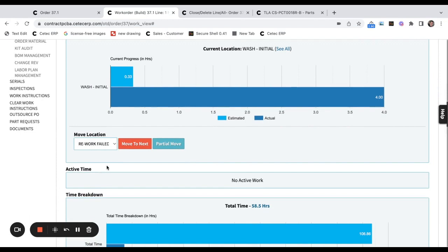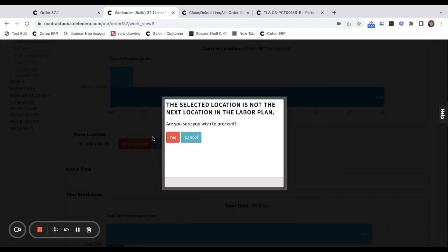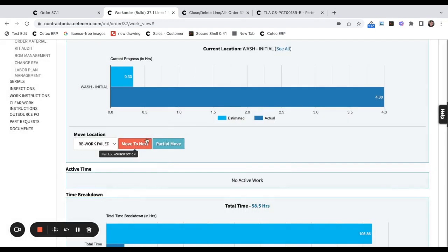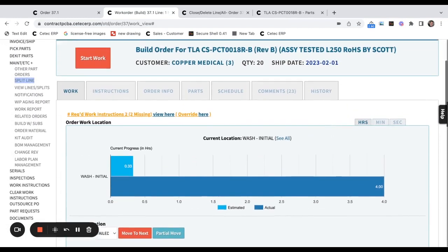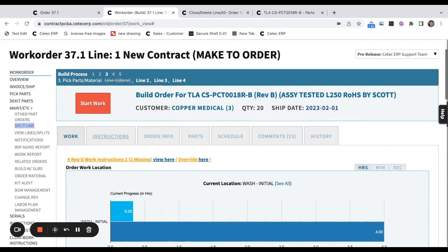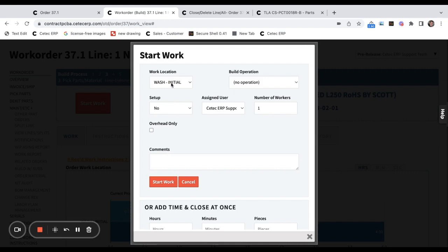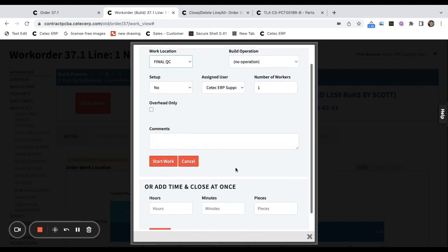If you'd prefer to keep the work order all together, you can status the entirety of the work order to a rework stage, even though only one assembly may be actually being reworked. Alternatively, you can keep the work order status as is in the inspection stage and simply have a production employee clock time of pieces through the rework stage using the time tracking and pieces complete feature.